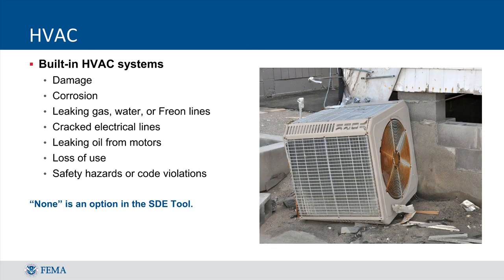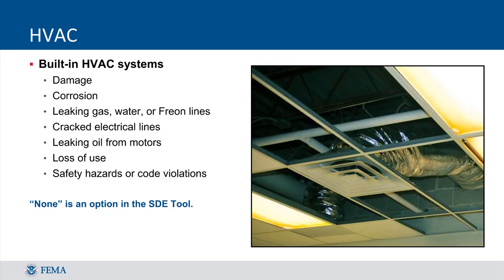The final damage element is the HVAC system. As noted previously, only built-in HVAC units are evaluated for damage. Window units or other portable heating or cooling units should not be counted in the damage assessment. For built-in units, be sure to consider the entire HVAC system and not just the compressor unit that may need to be replaced. In many cases, while the compressor is damaged and needs to be replaced, other features of the HVAC system may be in good working condition, and the damage percentage should be adjusted accordingly.